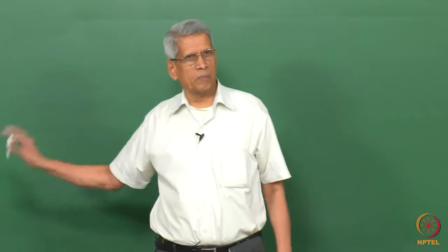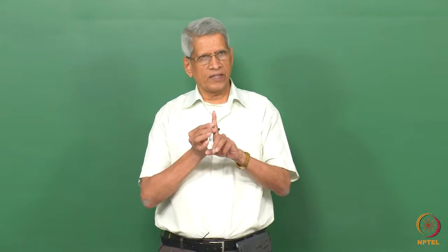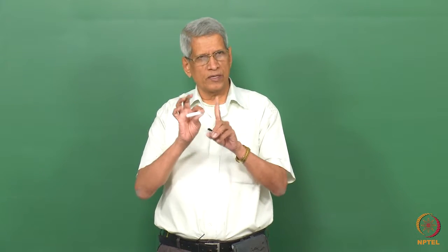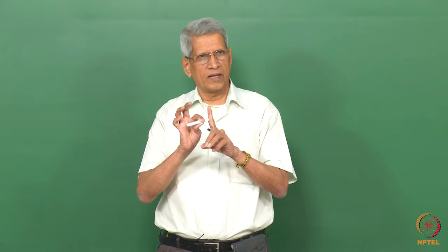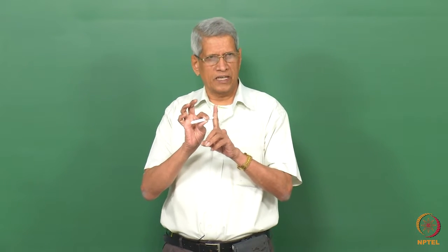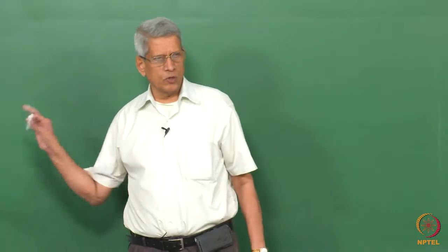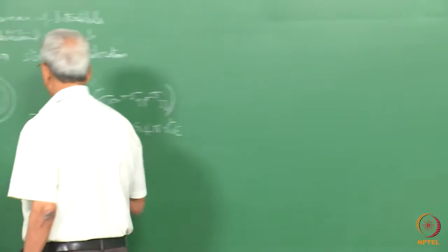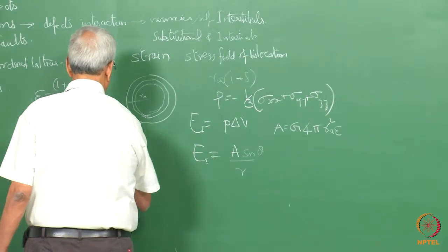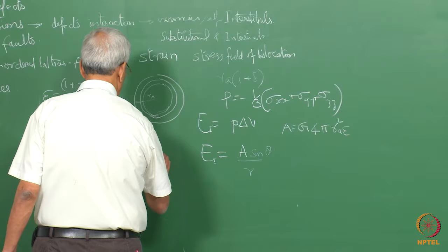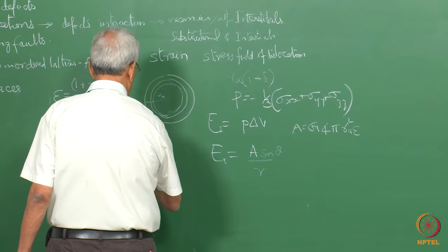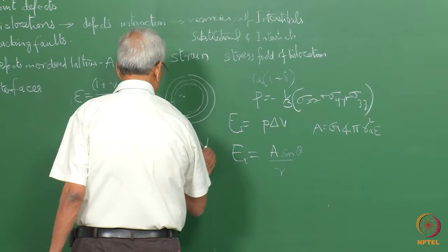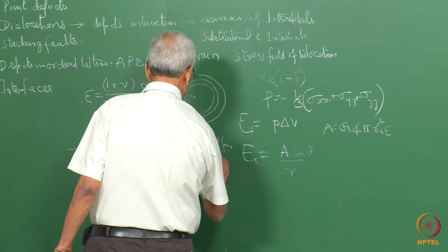Here we are looking at the other part of it. When they are even further away, there is an interaction. When the defect comes as close as possible and joins with it, that's the maximum energy gain, right? If you look at what this interaction energy is, this value I think is about 3 times delta, which turns out to be in eV for most of the metals.